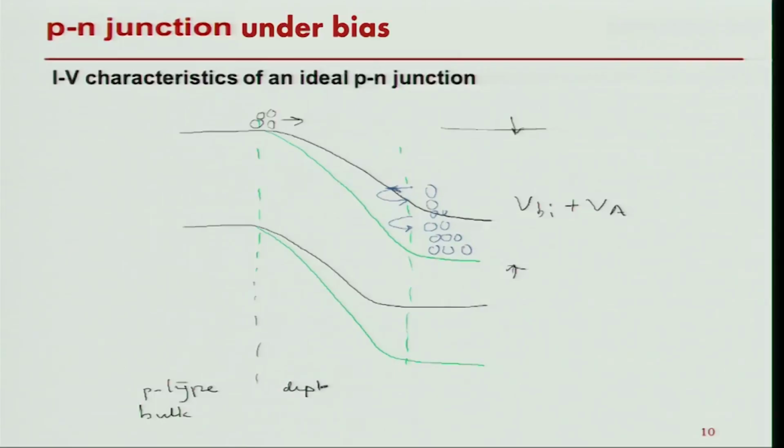This is the depletion region, and this would be the N type bulk region, again with negligible field here. So, I will be looking at the continuity equation in these 3 regions, solving it and trying to figure out what would be the current flowing when I put a device in a forward or a reverse bias. That would be the strategy.